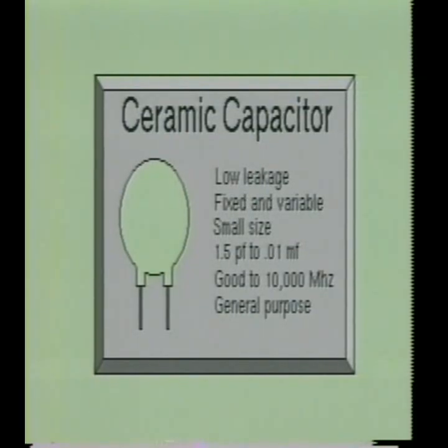The working voltage of the ceramic capacitor is about 500 volts and will operate at frequencies up to 10,000 megahertz. The ceramic cap is used as a general purpose capacitor.